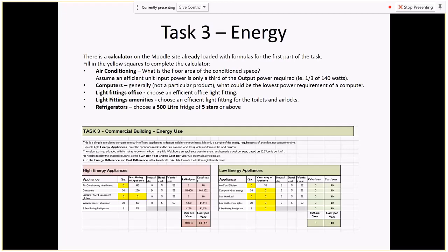Divide that by, let's say 125 per 100 watt fitting. I'm just pulling things out of the air there. So we get to our number there, and then we put in 100 here for our watts, and we get an astronomical figure at the end for that. Or we look at how many low watt LEDs we can get away with in that space, and then put in the watts of those.